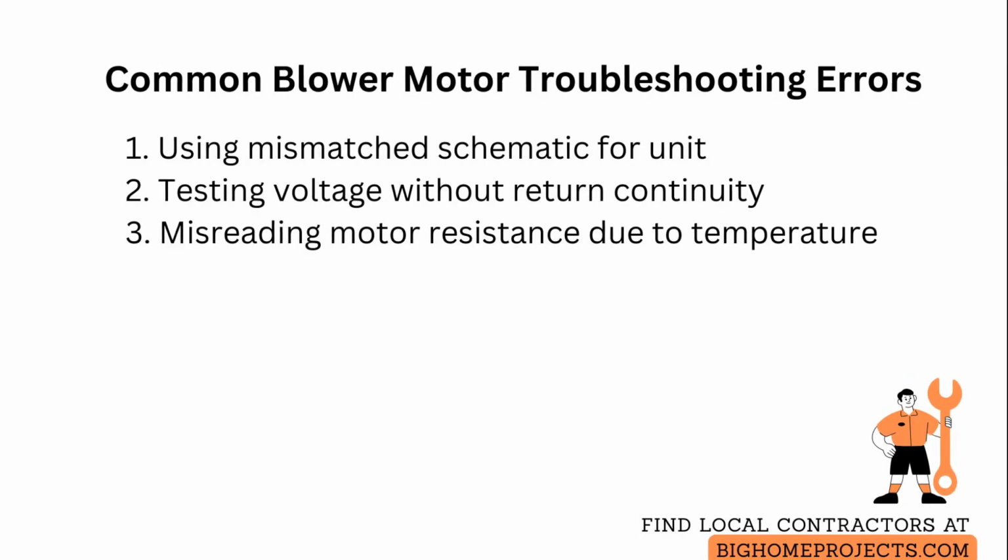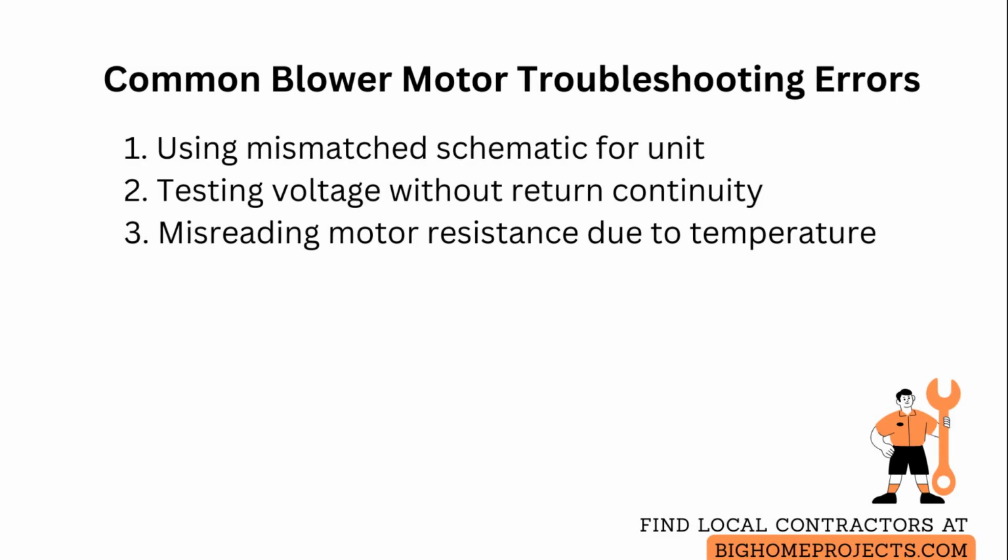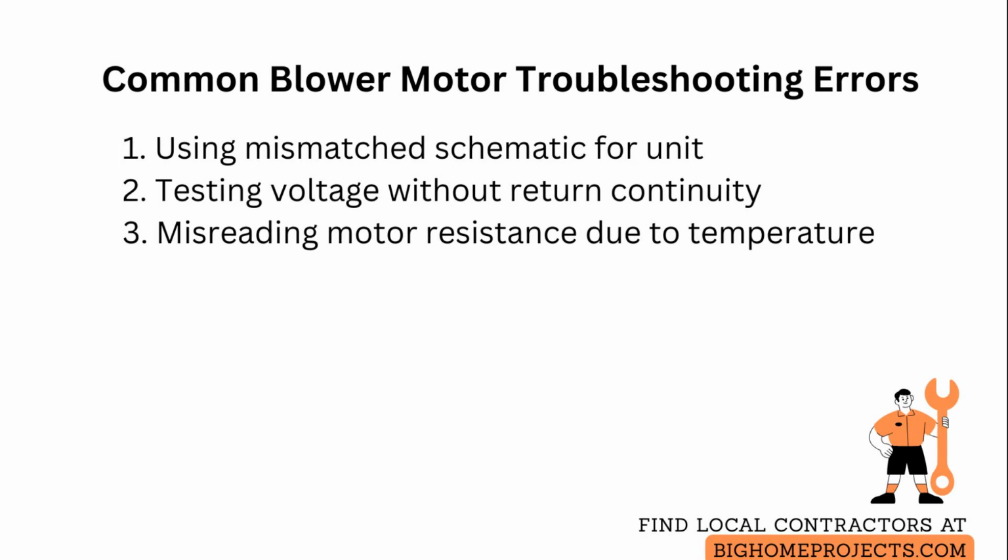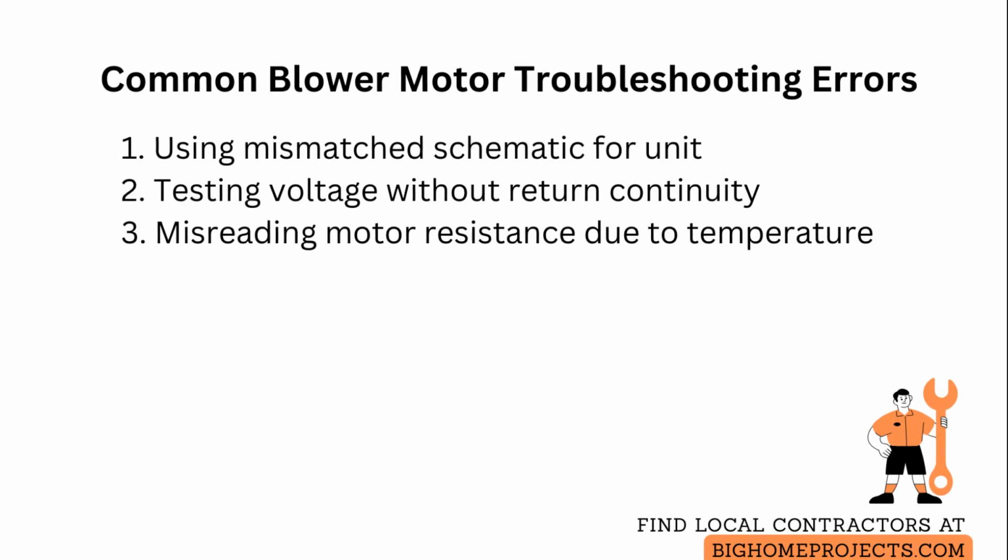A common mistake is trusting a schematic that does not match the installed unit because field modifications or replacement parts changed wiring. Solution: verify wire colors and terminal designations at the control panel and update your reference before troubleshooting.